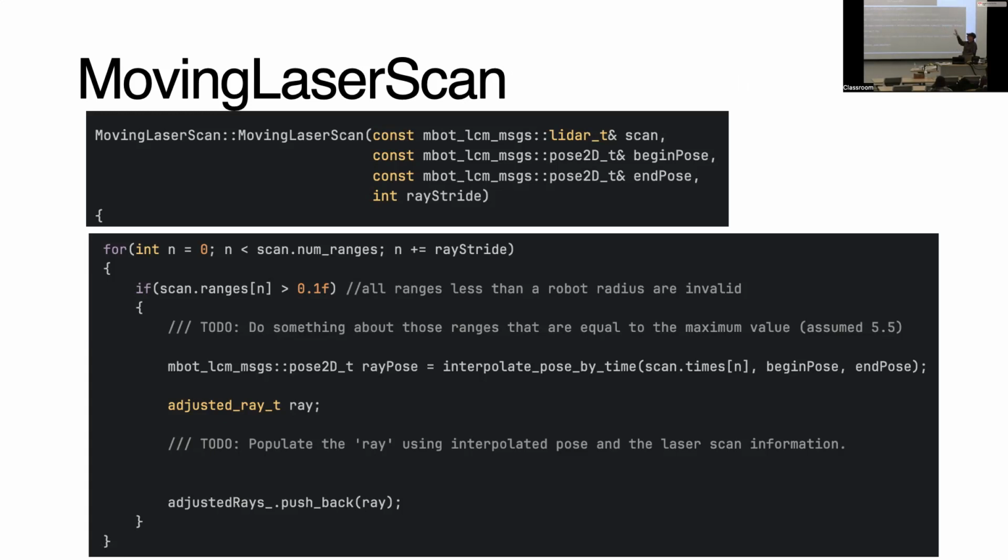Later, we're going to see how next time we're going to look at localization. So this mapping algorithm assumes that we know exactly where we are in space, but that is not necessarily true. We don't know where we are in space unless we haven't moved yet, right? Because when we start, we know where we are, we're at the origin. And then as we move, we don't really know where we are. We have an estimate of where we are because we do calculate the odometry. But if you were to take all the laser scans and just use the odometry as your pose, do you think you're going to get a nice crisp map?